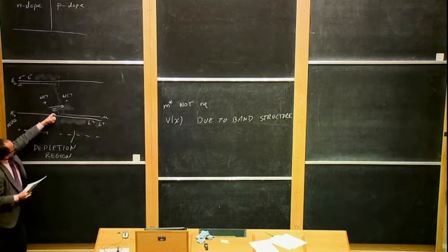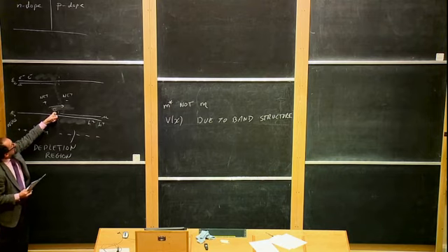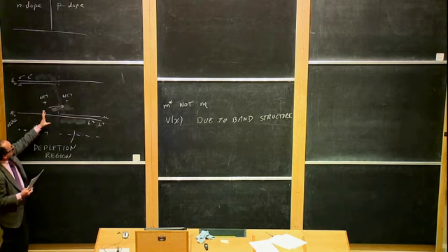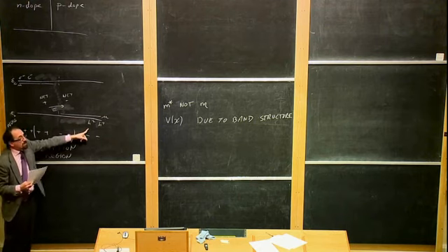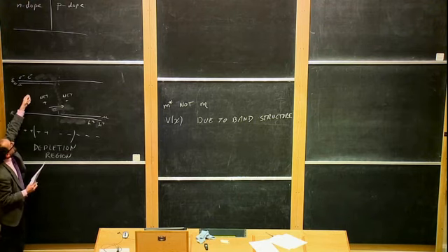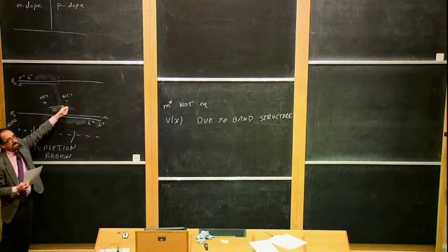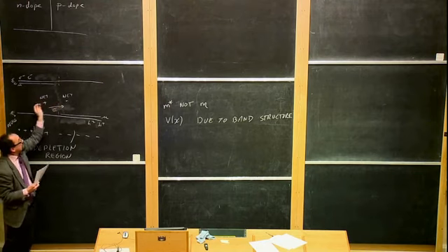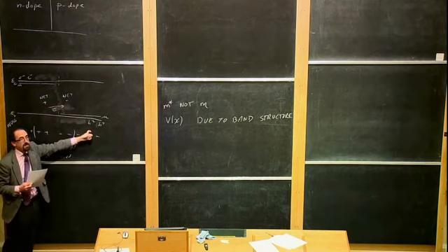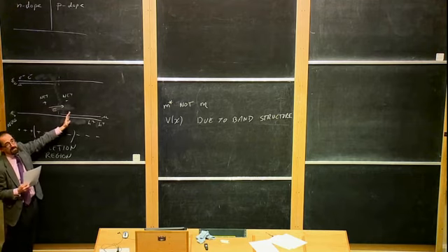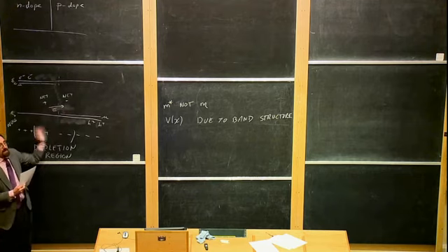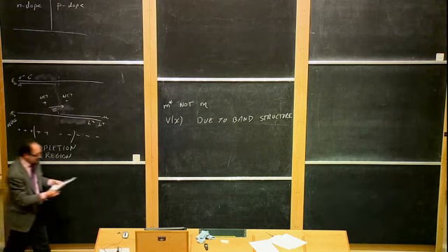So there's an electric field here that we're building up, and as we annihilate more charges here, we end up with more and more electric field. And that means if we want to take one more electron here and annihilate one more hole here, we first must climb up a potential hill, an electrostatic potential hill, to get past this electric field to reach the hole here. At some point, this electrostatic potential hill becomes too big, and we can't get over it, and we can't have any more annihilation.